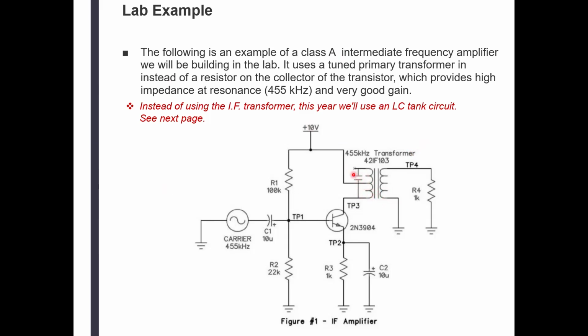So here's a tank circuit. Instead of that resistor, here's what's happening. The tank circuit is tuned to a specific frequency at which it resonates. And once that frequency is applied to the whole circuit, then the whole thing becomes alive. The resonating frequency of that tank circuit is going to produce a huge, huge signal.